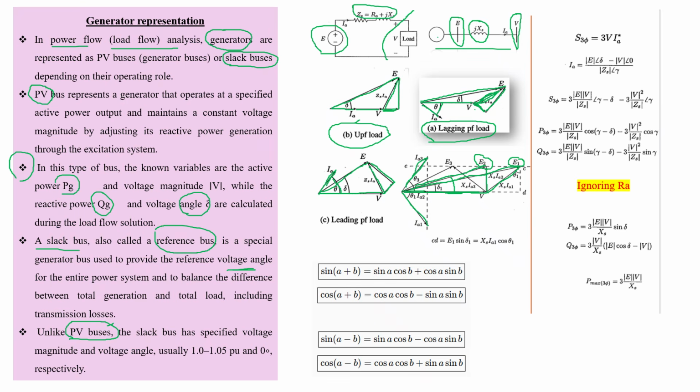On the same principle, since the current is here and the terminal voltage is here, the voltage drop due to this current is perpendicular to this current. So if we draw a perpendicular line, we have this, and at this point we have E3. Whatever the scenario is, the magnitude of internal voltage is dependent upon the type of load connected to the terminal voltage.